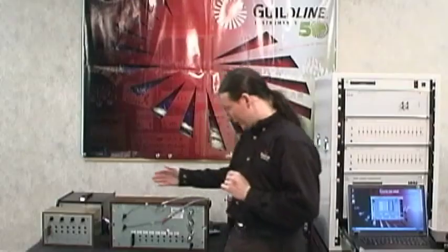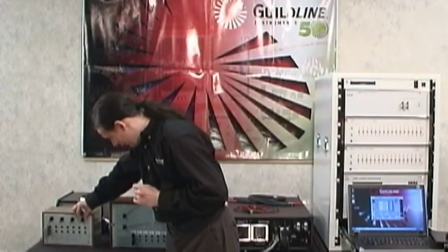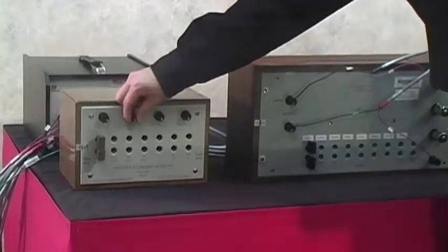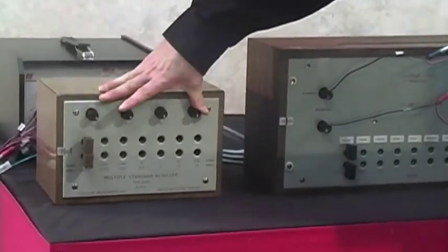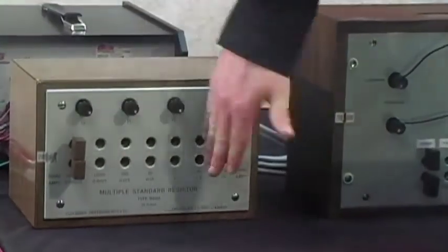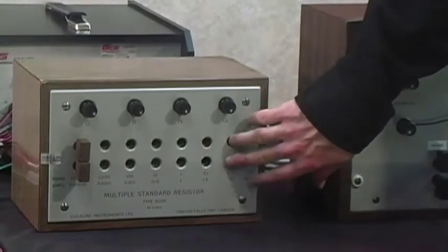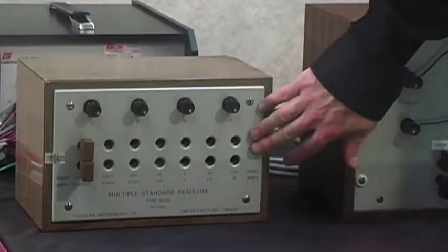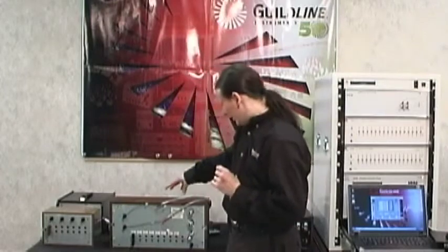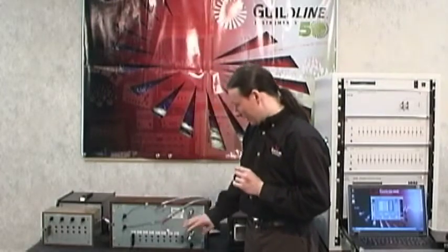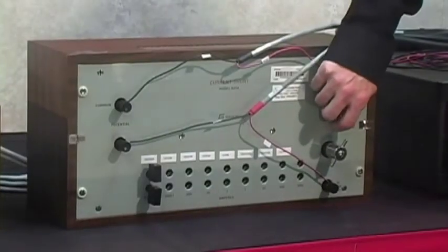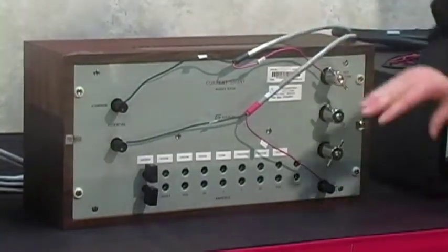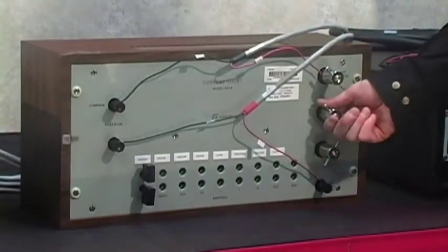For the smaller ones, like a 9200, you see that the P1 and P2 are in the middle, C1 and C2 are on the outside, and the connection is common for all the ranges, because this particular shunt doesn't really go that high in current, it only goes up to 15 amps. But as you get to the ones that can withstand quite a bit more current, like the 300 amp shunt here with this 9711 or 9211, they have to have separate terminals to withstand that amount of current.